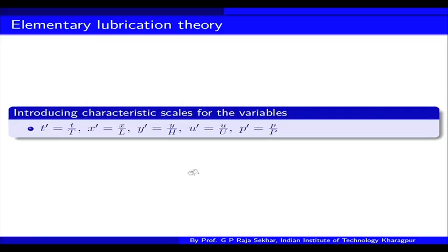Now, we would like to fix the corresponding non-dimensional length scales. So, for t we are introducing a characteristic time, and for x, since we are considering, let us say, rectangular geometry, parallel plates which are separated by distance h, along the direction of the flow we have L, and perpendicular we are using the distance between the plates. And for u, velocity, assume you have a unidirectional flow, or in general flow along the x direction.